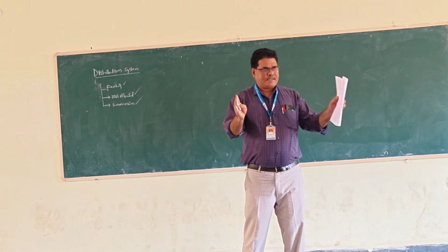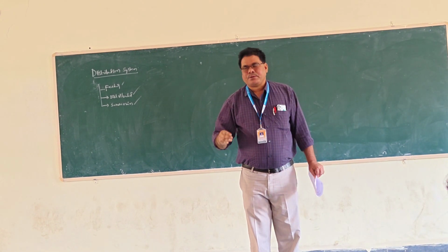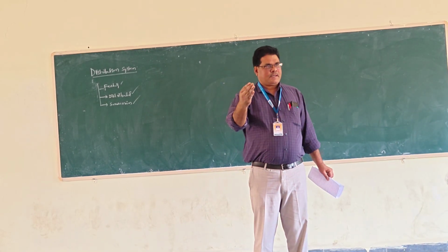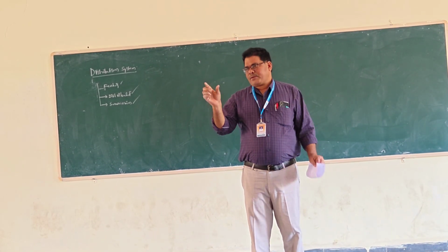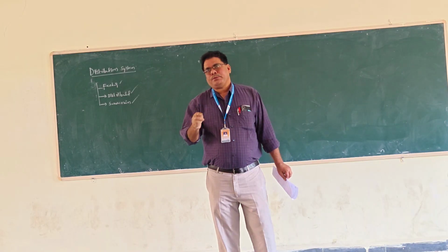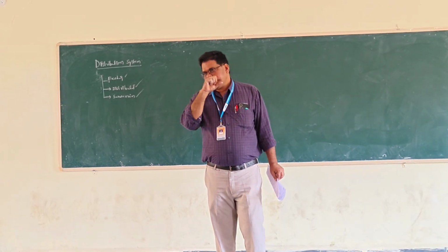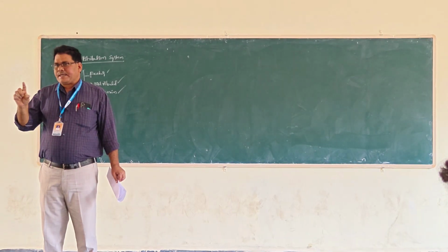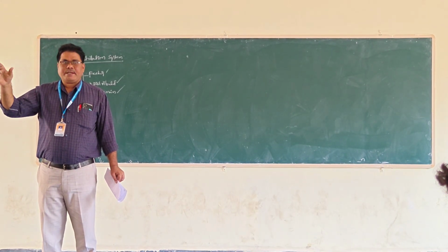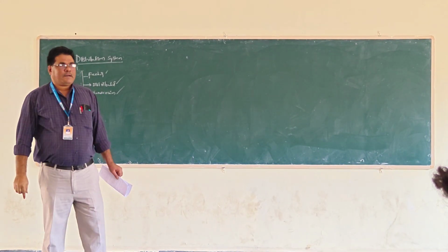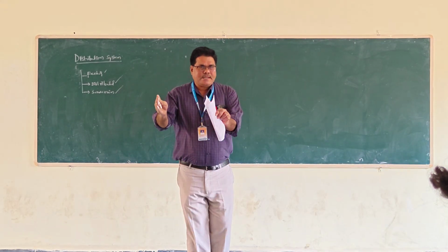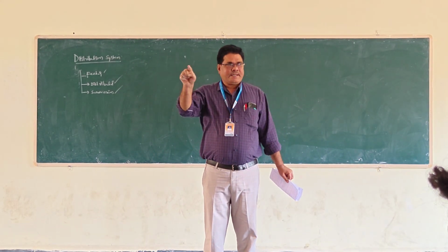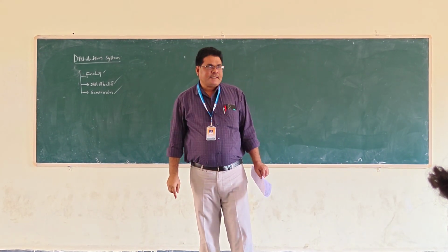One substation is there. From the substation to one area, one village or one state, from the main substation to the area, there is a conductor. A feeder is a conductor which connects the substation to the area where the power is distributed. Substation to one village, the main line, a 33 kV line, is called a feeder.